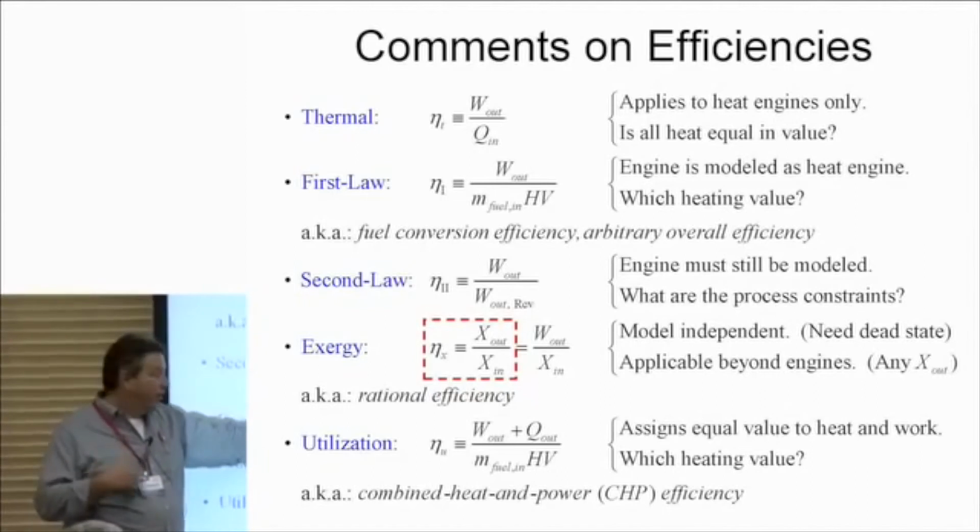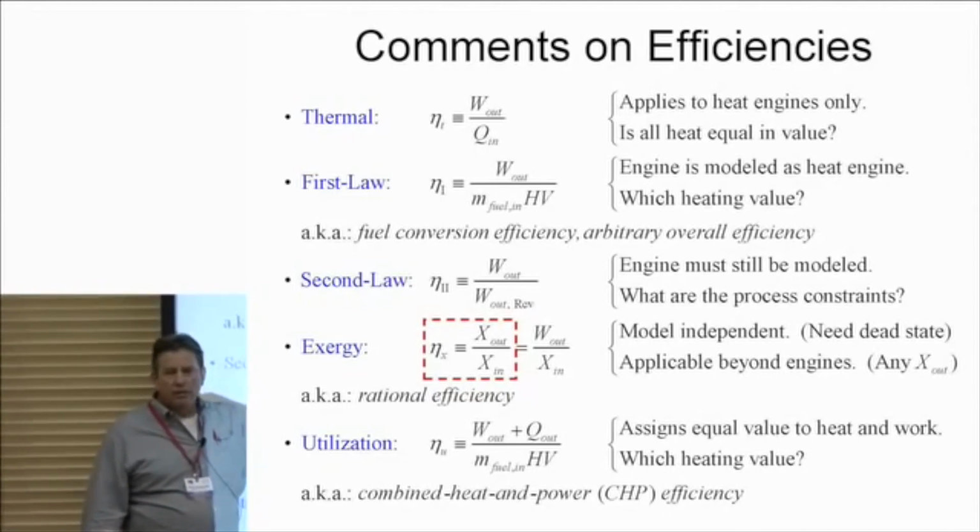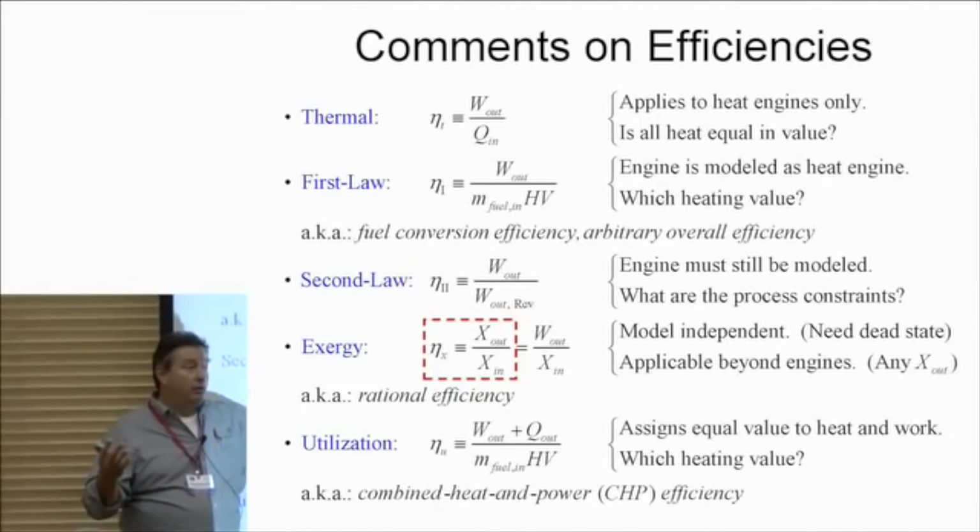If it's an engine, what we're looking for is work. And the exergetic resource, is there exergy with the air coming into the engine? And going into the turbocharger, it's got no exergy. It's an environmental species, right? And even drawing it from the environment, I have to do work to draw it from the environment. So there's nothing that comes with the air. It's just the fuel. So it really is the chemical exergy of the fuel that we're putting down here.